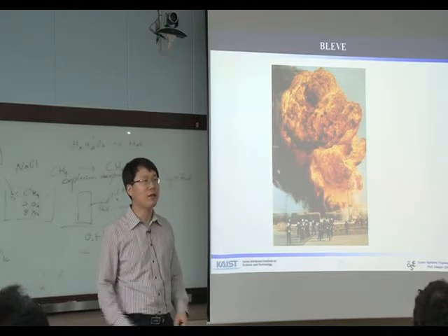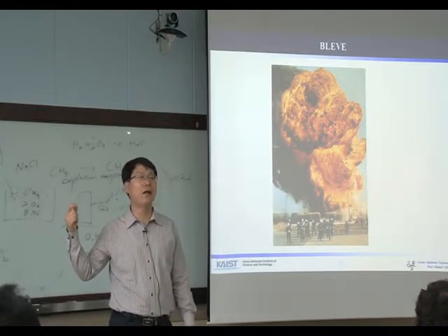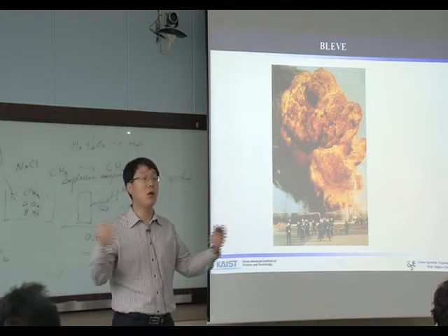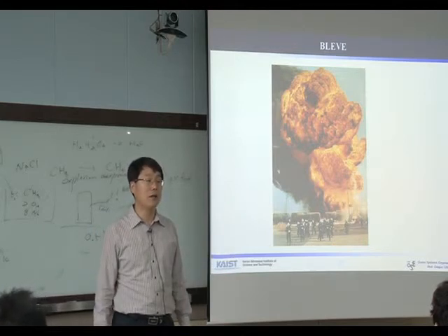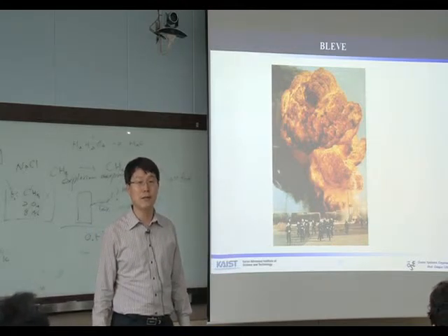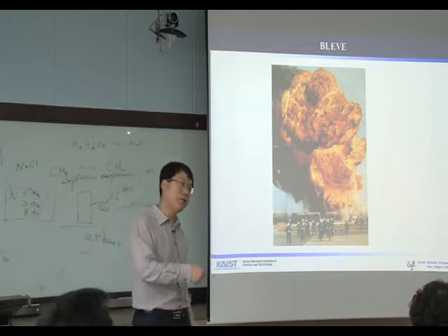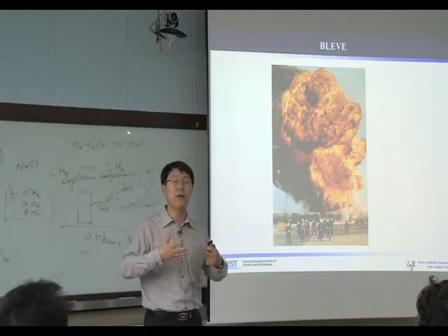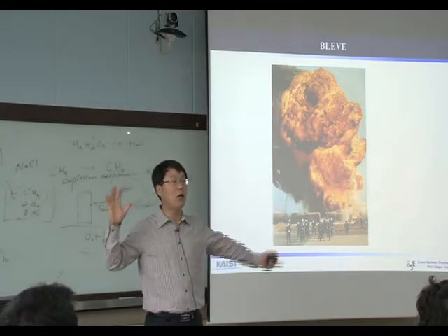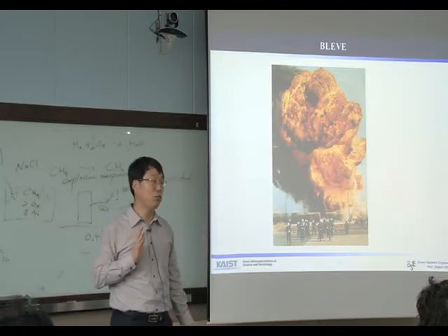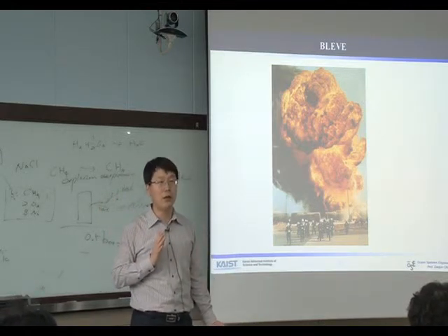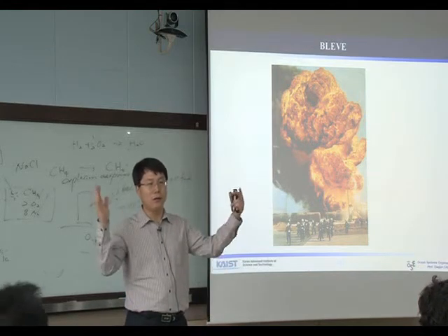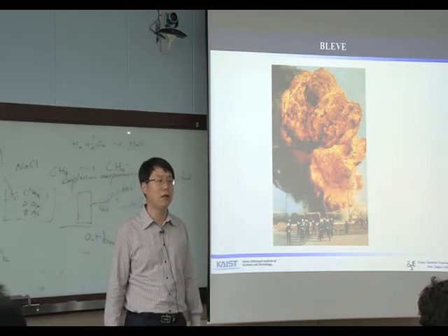So things like a car crashing into a building and there is an explosion, those kinds of things make no sense. The liquid should vaporize. So we need some time for the gasoline to vaporize and make a cloud whose concentration should be between LEL and UEL. Then there is some ignition source. Then the cloud can explode.